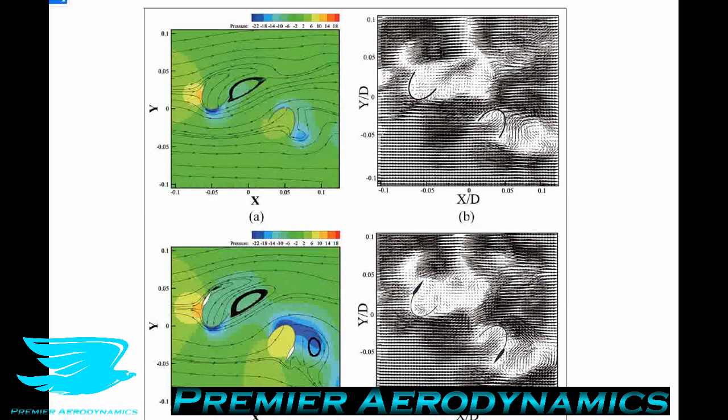But what we did learn is that putting tiny little NACA 0018 airfoils on the ends of the blades has significant effects on the blade's starting performance, both when it's static and rotating, sometimes for the better, sometimes for the worse. And with that, my little aerodynamicist, we come to the end of this podcast.